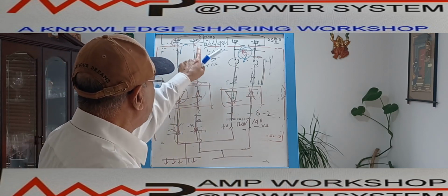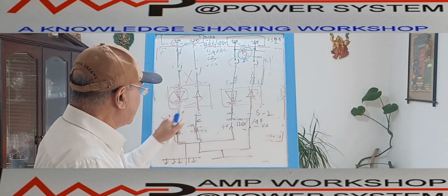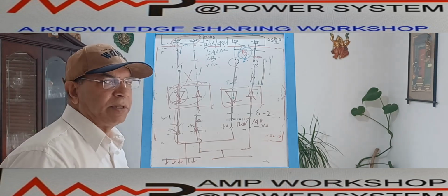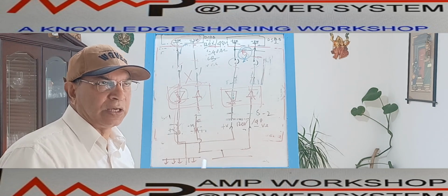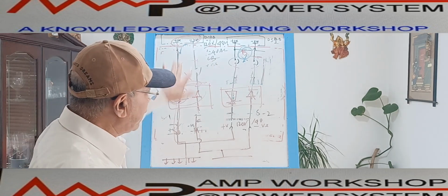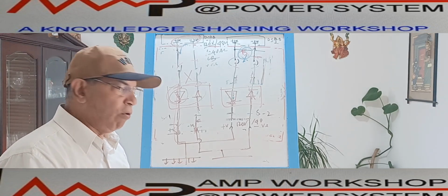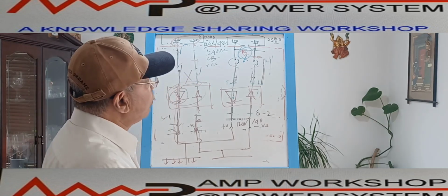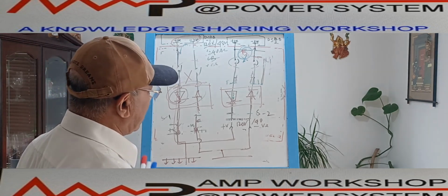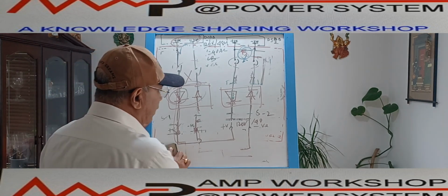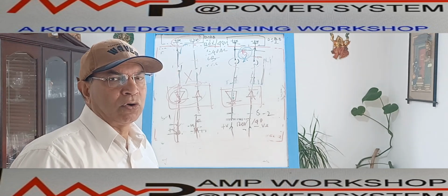The diode rating should be suitable for the total power rating. We can use this in case of DC supply. AC supply is not possible because we cannot directly hook up AC supply, due to the frequency and power angle difference for the single phase supply. So this is the way we can make the changeover scheme for the DC control power and AC auxiliary power. With that, we are completing the schematics. Now we'll discuss the single line diagram and the 3-line diagram in the next video, and with that we'll be completing the switchgear control schematics.